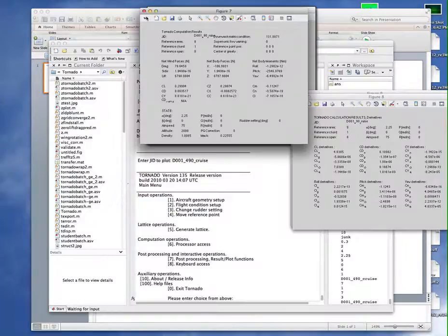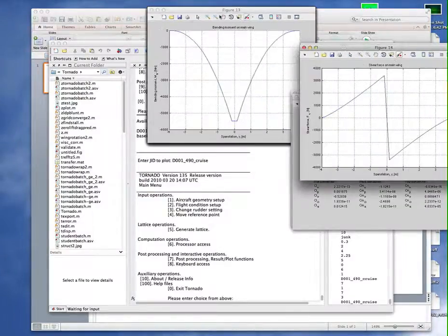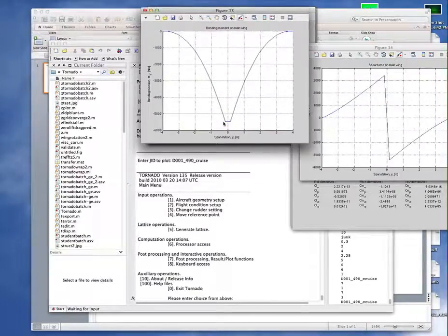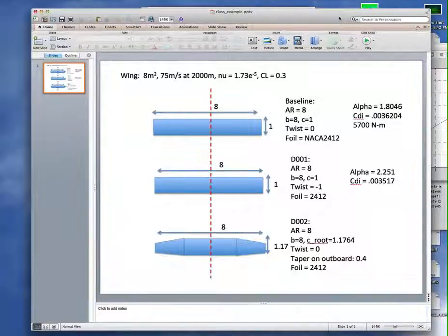Let's just check the bending moment. Bending moment is smaller, which makes sense too. It's at about 5,400. Again, you would have to zoom here. I'm not going to do it now. Zoom in and count the dots to get this 5,400. Call it.